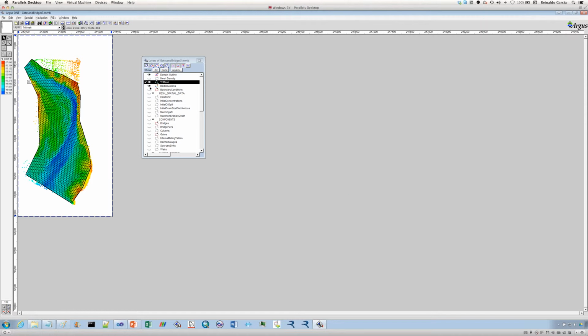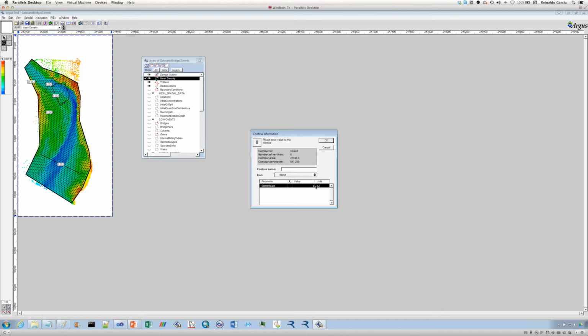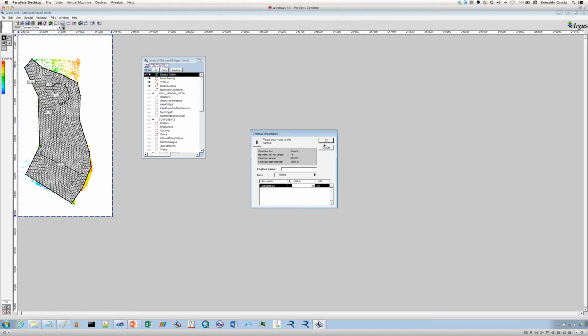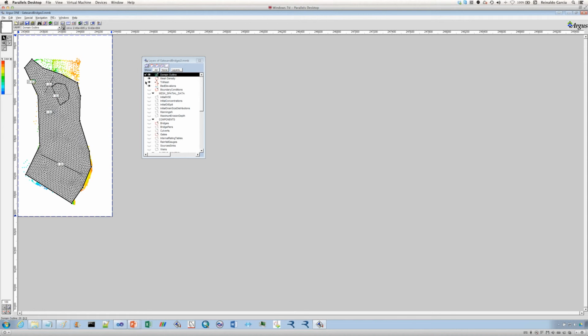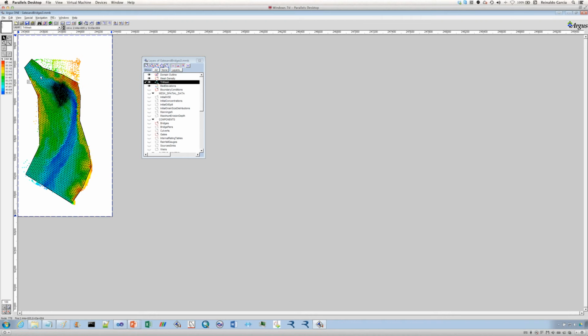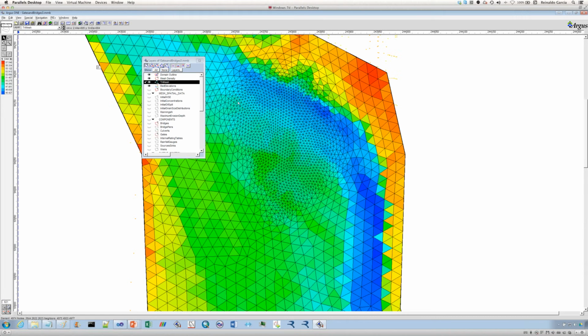And the mesh can be refined very easily by adding polygons or polylines. So, for example, if you wanted to remesh with a higher resolution here. For example, I have 20-meter resolution in general, and I want 5-meter inside this polygon. You remesh, and then you have a much higher resolution here in this area of the polygon.